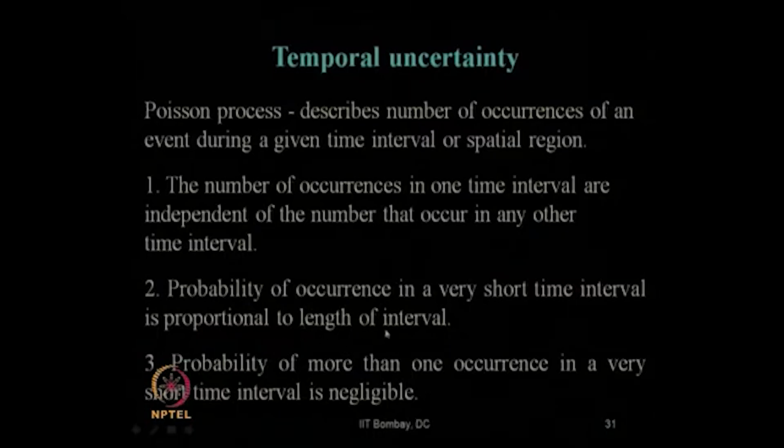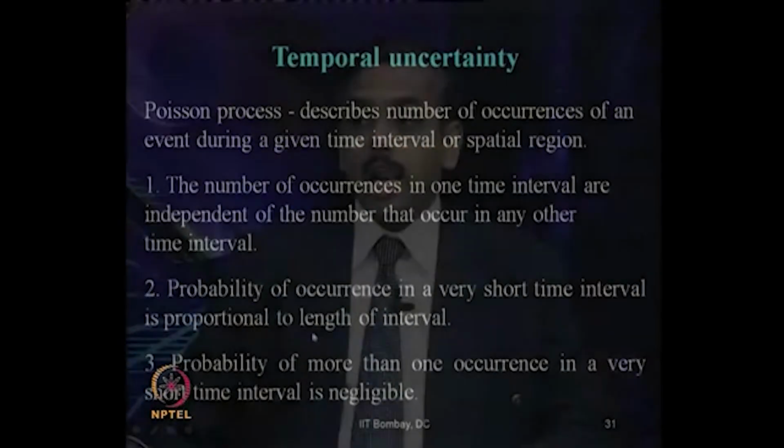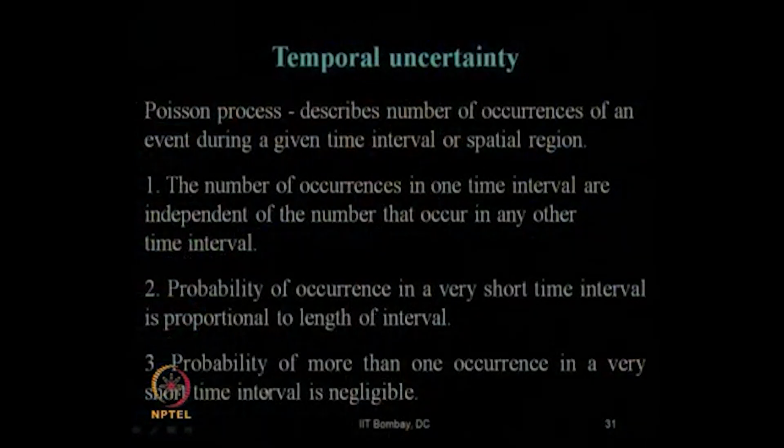So, that means automatically if you have a longer interval of any earthquake, you have more probability. Can you see how we relate also the duration of earthquake through this Poisson's probability distribution function? And probability of more than one occurrence in a very short time interval is negligible.